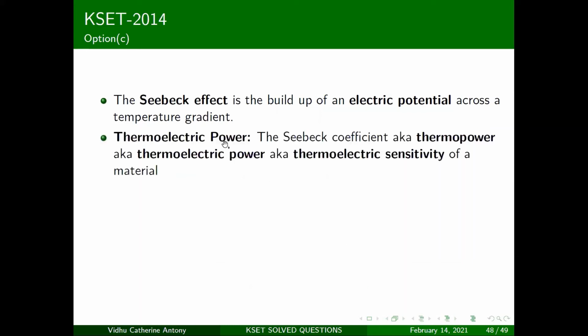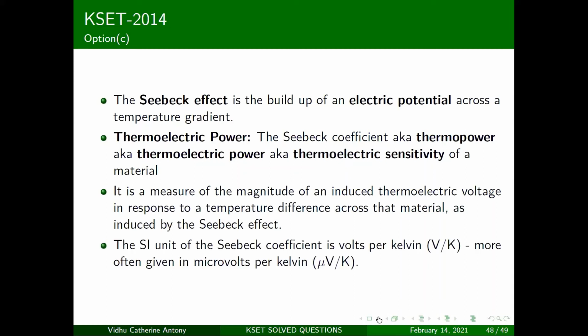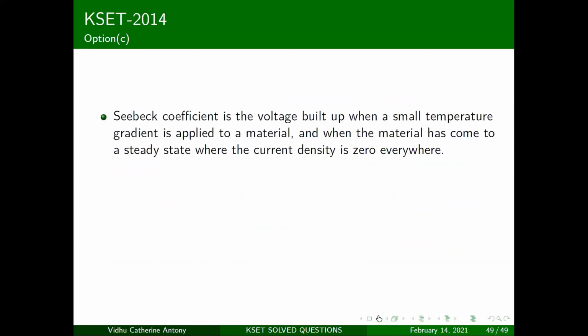Okay, so coming to thermoelectric power. Thermoelectric power is basically your Seebeck coefficient. It's also called thermopower or thermoelectric sensitivity and so on. It is a measure of the magnitude of an induced thermoelectric voltage in response to a temperature difference across that material, as induced by the Seebeck effect. The SI unit is volts per Kelvin, but an easier way to talk about this is in terms of microvolts per Kelvin.